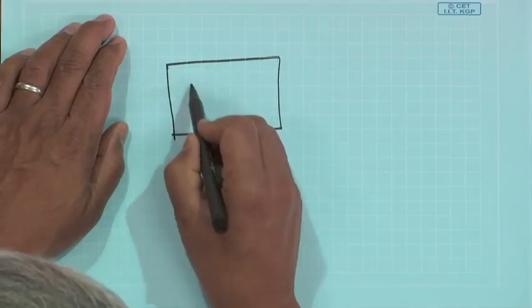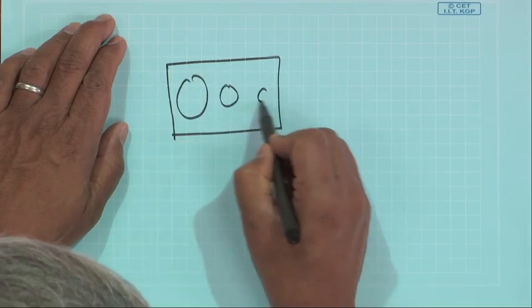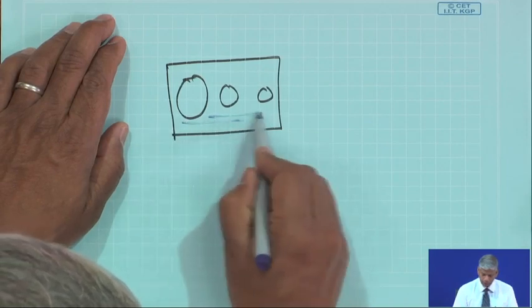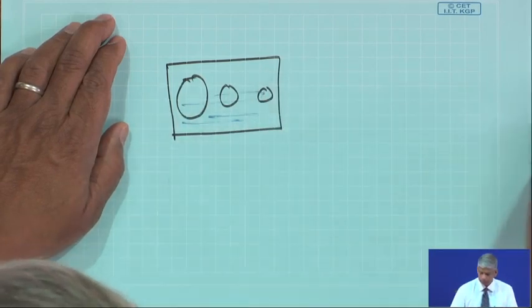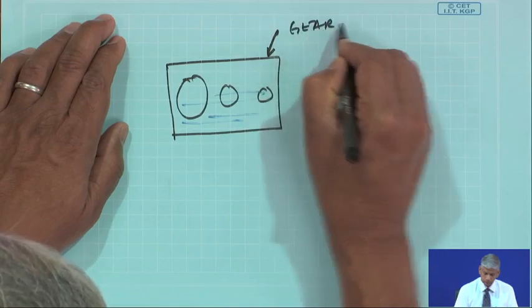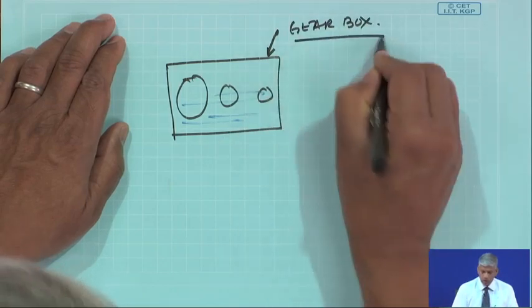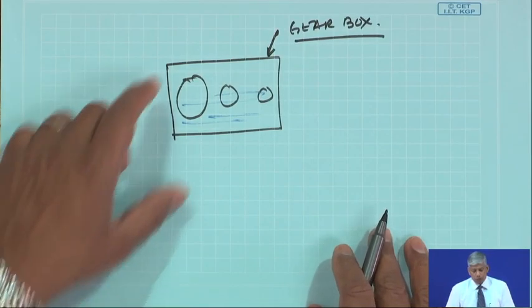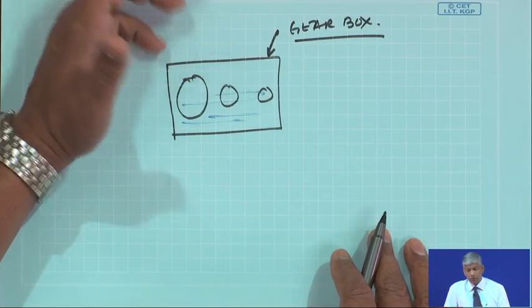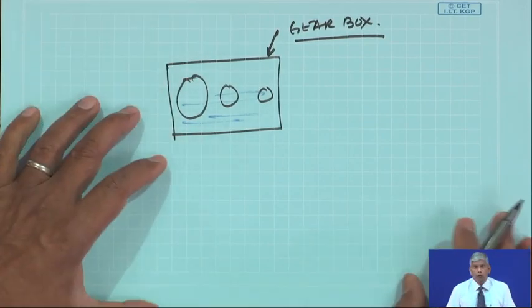But for our sake of discussion, we will say that all you need to do, suppose I have a large gearbox, there is a gearbox on the outside and there is lubricating oil. By now we have studied that by putting a vibration transducer and doing a real time signal analysis, in situ measurements, I can find out faults.